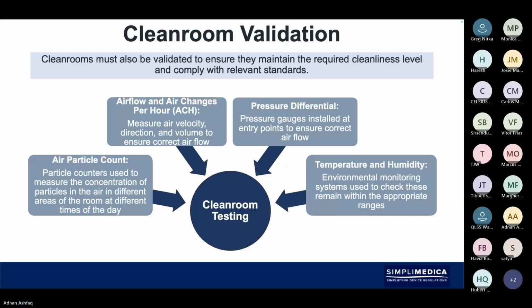So even in the atmosphere, if it's a wet, damp day, it can affect the pressure differential in the clean room. And I've had situations like that, having also worked in the pharmaceutical industry, where we've had to put placebo powder into a bottle as part of packaging validation, where it's been a damp day. It's been absolutely impossible to try and control the volumes to make it placebo. It can look as if the powder has expanded, but the actual weight of the powder is exactly the same as a bottle that looks more full and one that looks less. And the reason for that, when we did some troubleshooting on this, was because of pressure differentials.